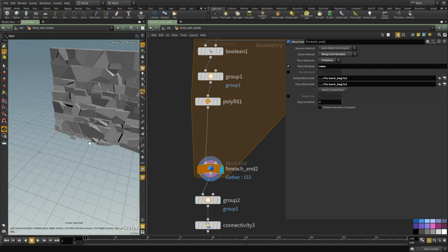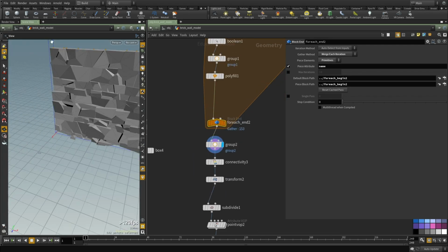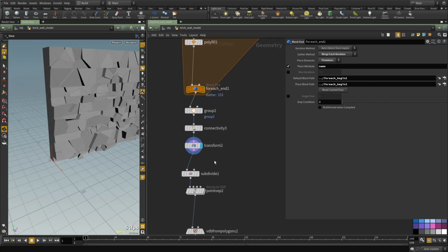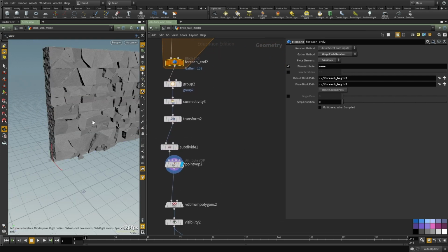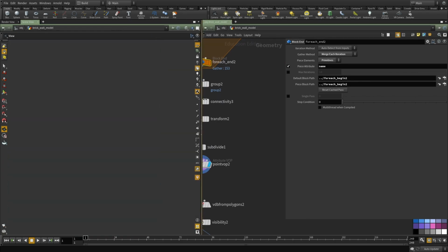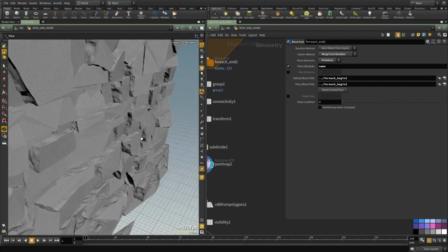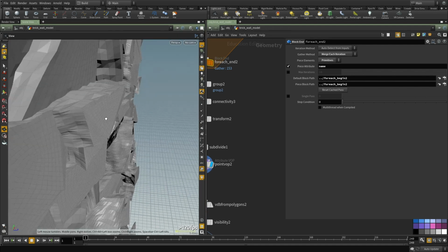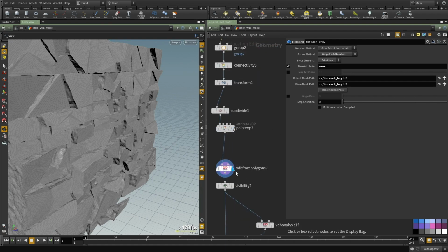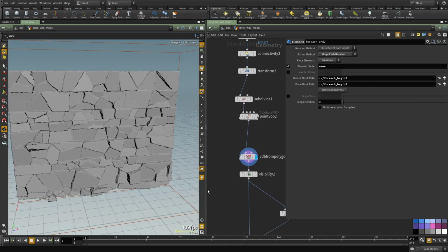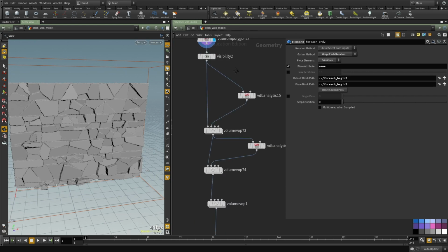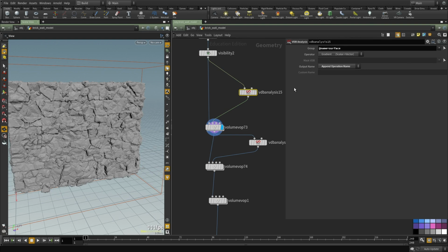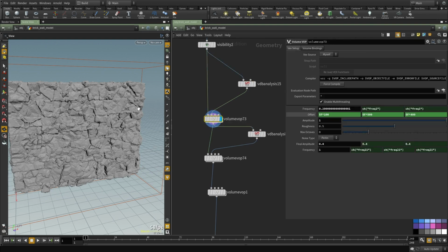There's a lot of interesting details inside the base geometry, which is actually very, very simple, just polygons at the moment. And then I subdivided that and added a little bit of noise to break the edges. So I'm not changing this vector, just these faces, so up and down. And then did a VDB from polygon for all of that. Don't worry about this yet. And then VDB analyze to compute the gradient of this.